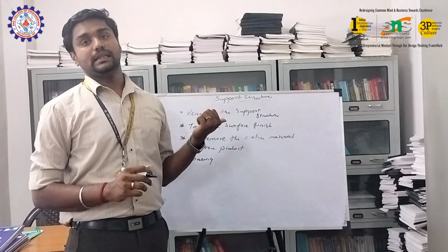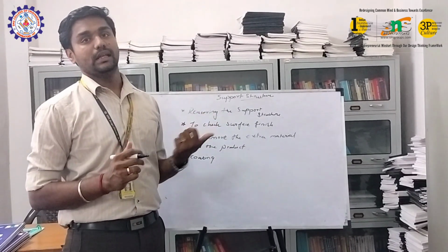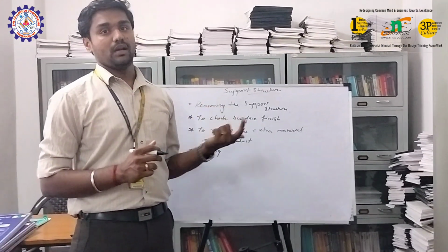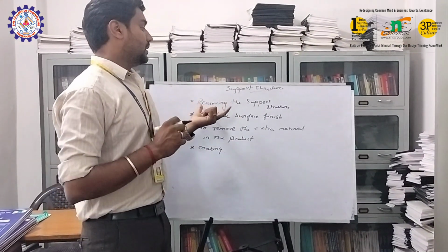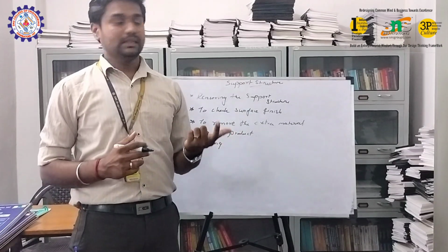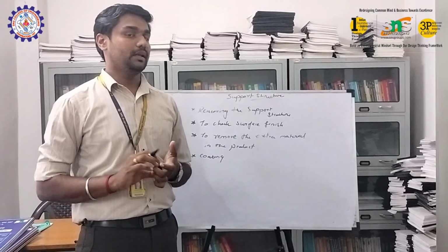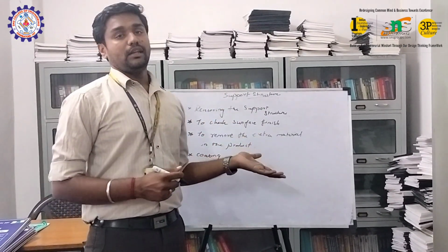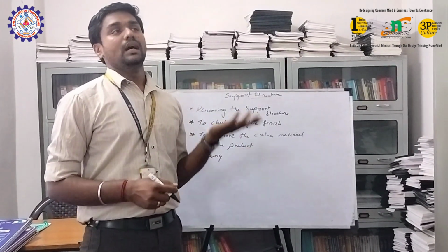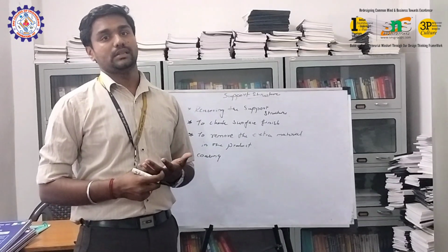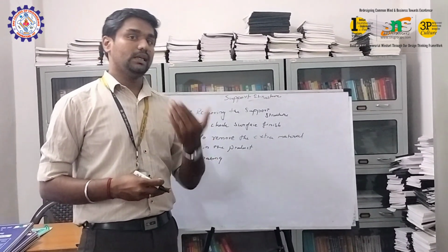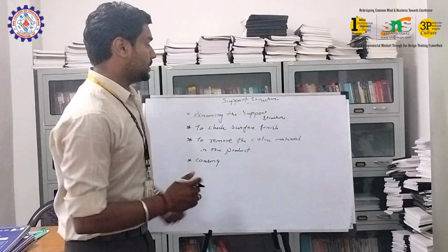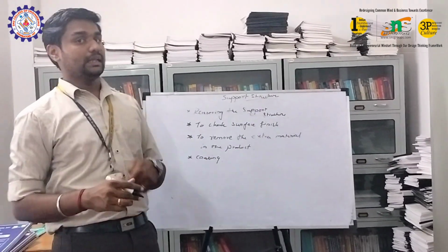Removing the support structure is the major post-processing technique, where the support structure has to be removed from the product, which can be very difficult when the product has a complicated structure. In fused deposition modeling, the most commercially available 3D printer, support structure removal is somewhat easy compared to other technologies. In metal additive manufacturing, stereolithography apparatus or ceramic based printing, removal of support structure is a tedious process because the support structure interbonding with the product has more strength compared to fused deposition modeling. In FDM, support removal is commercially easy compared to the other 3D printing technologies.